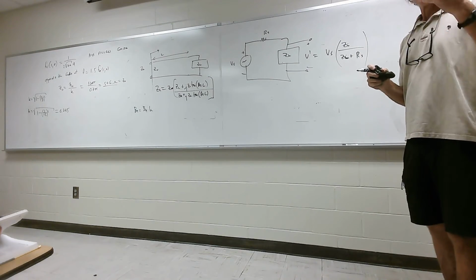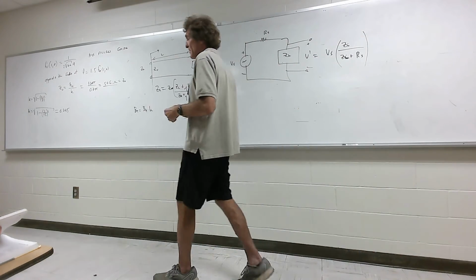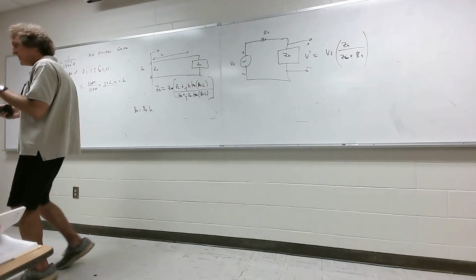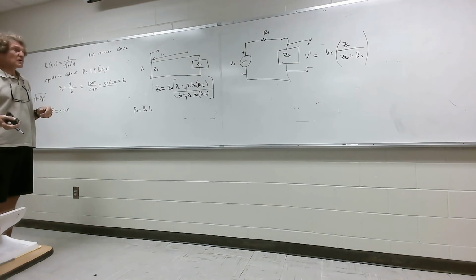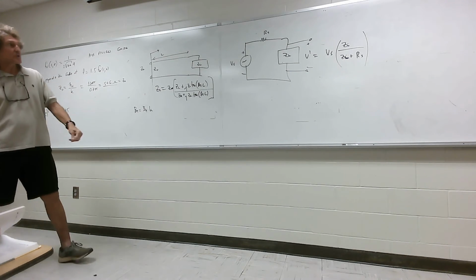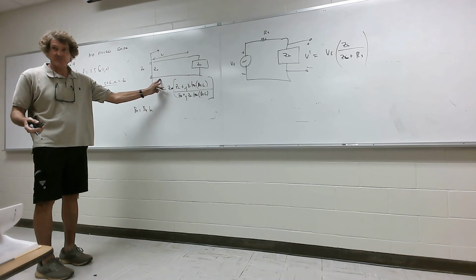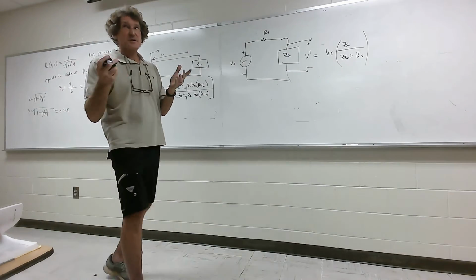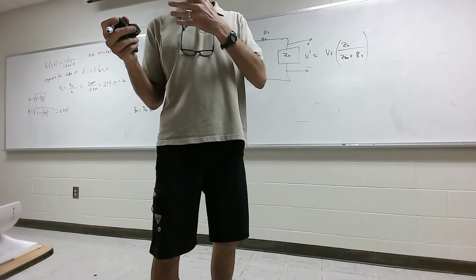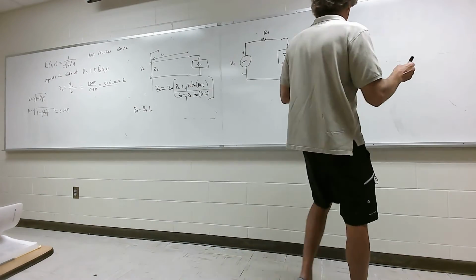You remember? Now, inside the guide, the way they actually solve it, you don't have to solve this in terms of the electric field's value. There is, in fact, for the TE10 mode, a measurable voltage from the top of the guide to the bottom. Follow me on this? If you literally put a probe in there, you could measure that. So it's much the same as a transmission line in terms of how we go about defining what happens inside.